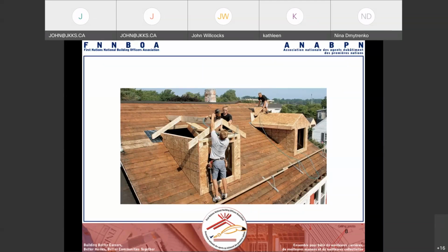That board going across is basically those metal roof jacks, and what they do is put a plank across, sometimes depending on the slope of the roof, to help provide some footing, or we'll say something to basically stand on or balance against as far as doing the roof is concerned. But they still require safety harnesses, all 3 of them.